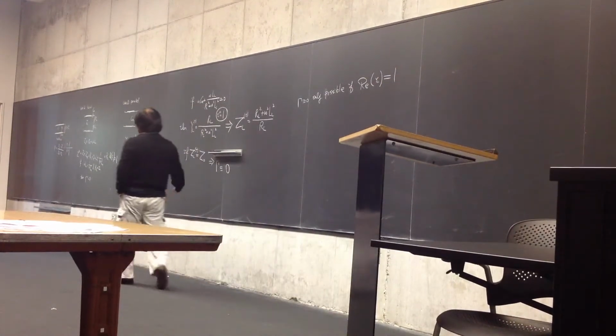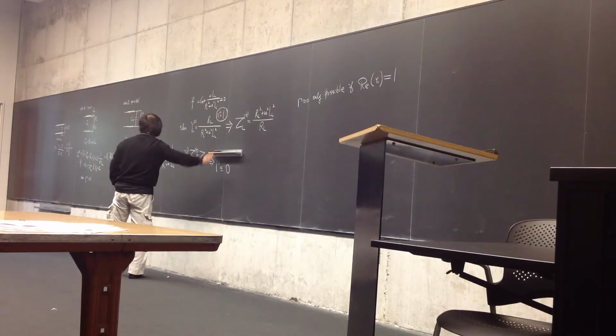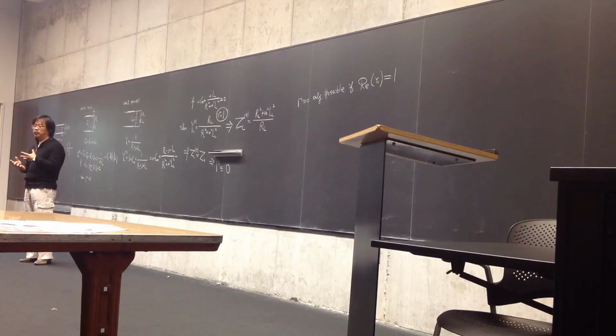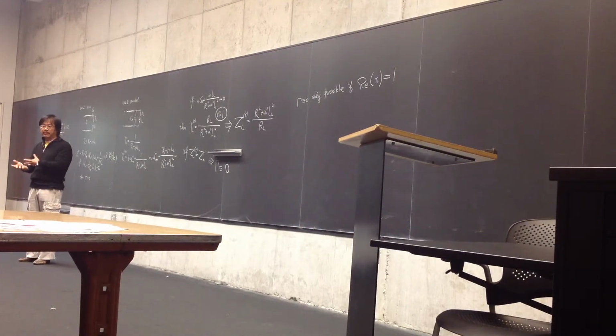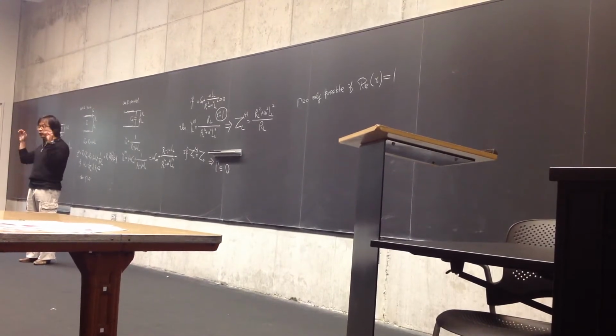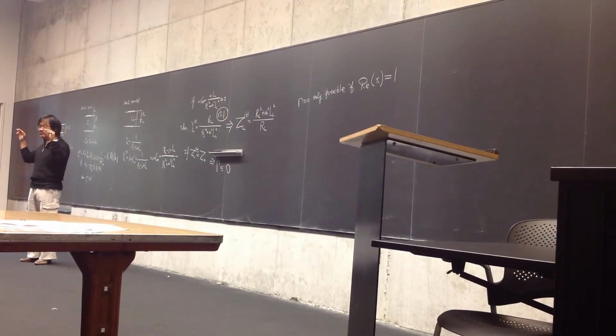So you see, just from your basic circuit and then the analysis, you can see there are two ways you can do the matching using an inductor and capacitor to cancel out the imaginary part, such that your total impedance, your total admittance becomes a real number.